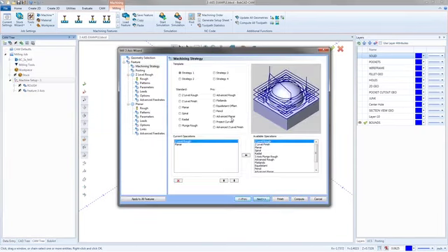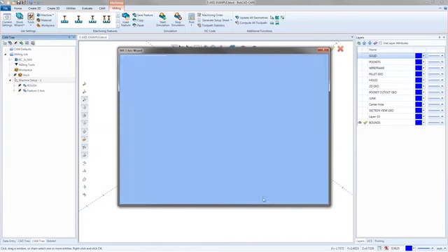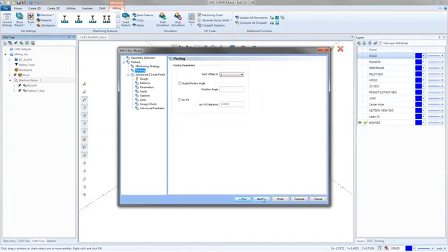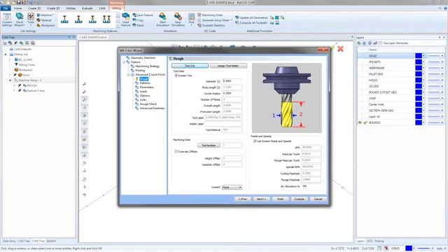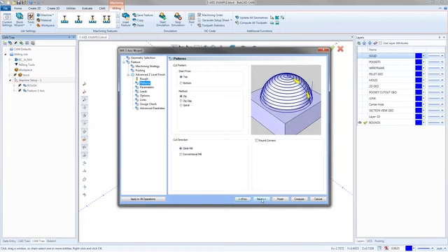So from here, I want to go in and do another advanced Z-level finish. I shouldn't need anything after the Z-level finish because there's no floor to this one. So I just want it to machine down. But I'm not going to be able to use a 1/2-inch end mill on this, so I'm going to switch it up. I think I set the radius to those corners at about 1/8 inch, so a 1/4 inch ball should be fine. We will find out here in a few minutes when it finishes calculating.